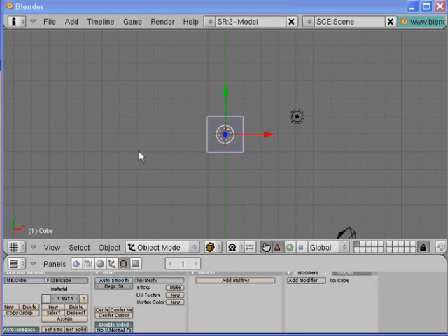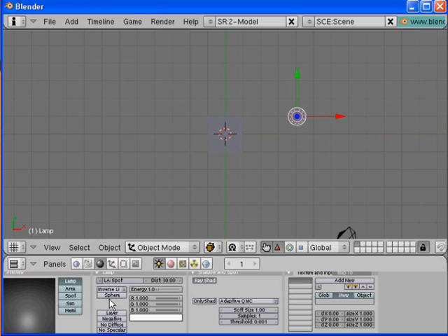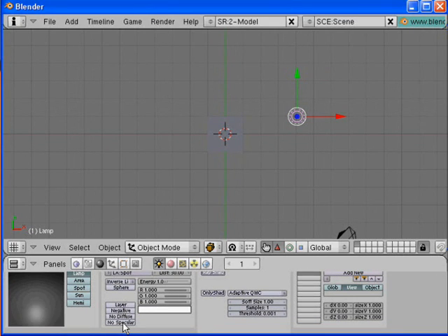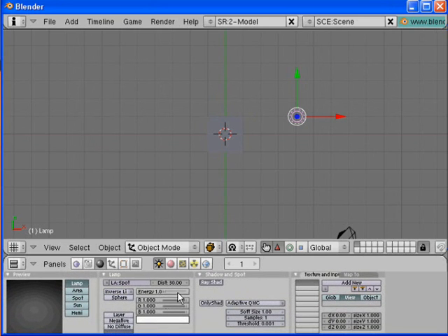So, first of all, to turn off the specular, you need to select your light, just by right clicking on it over here. Go into the shading tab, and just click on no specular, which is down here. And you will see in the preview, it starts to disappear when you turn it on or off. So next we will go through some better lighting.